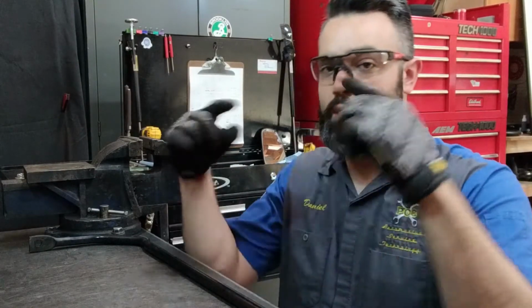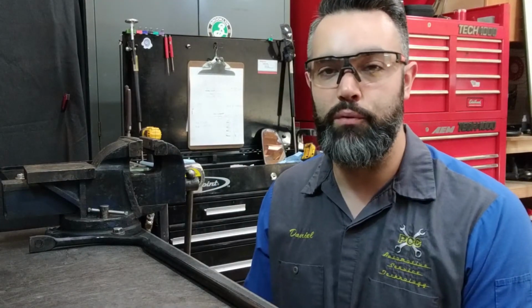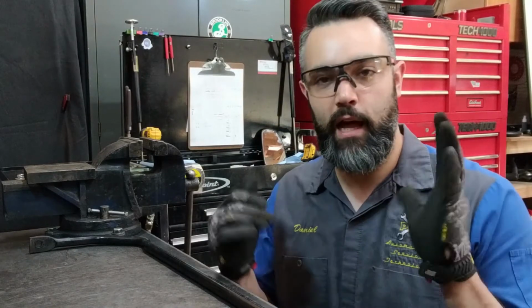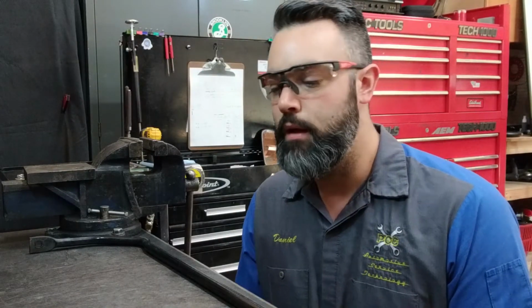The example on the Jeep: manually disconnect, tie the sway bar up to the chassis so nothing is hitting or binding, and it allows more movement of the chassis. On newer Jeeps or newer off-road vehicles, they may have an automatic disengage and engage switch that the driver can use to disengage the sway bar without even getting out of the vehicle.